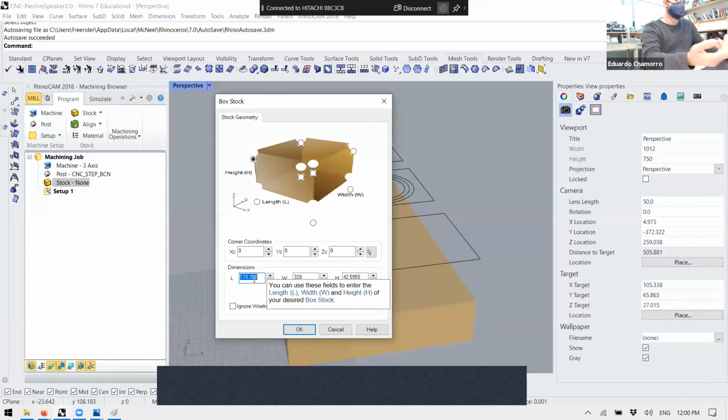What you just need to set up is the size of your material. Let's state a full size material and the thickness. For example, right now we are going to cut. So ideally, now we should go and measure the thickness of the material. Actually, I will bring a small piece of material. We're going to cut in this leftover. For the camera, let's measure it. Here, for example, this board is supposed to be 18. This is 17.47. Pause. Don't know if you see in the camera.